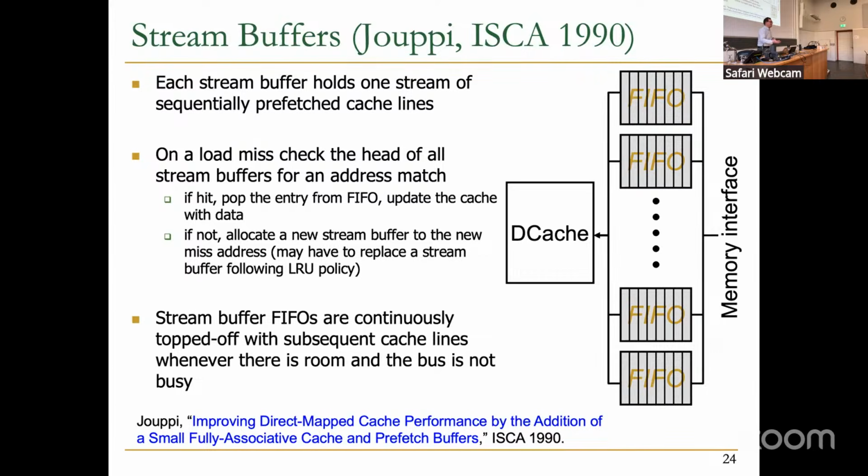Okay, this is one very particular implementation. It works nicely for access patterns that fit it. Again, if you have an access pattern with a stride of 4 or 2, you're in trouble. You need to modify the hardware, and you need to modify something else. So certainly people have proposed, okay, can we actually modify this for strides? And you can amend this such that FIFOs don't assume a stride of 1. You just detect the stride for each region, right? And each of the stream buffers, each of the FIFOs, operates using a different stride that's detected for that region.